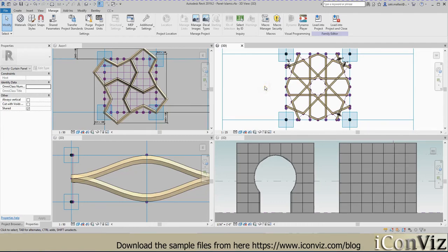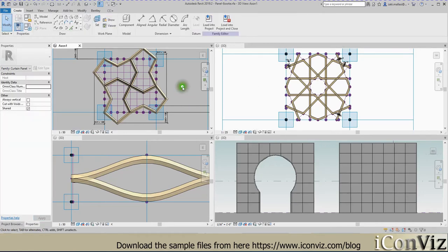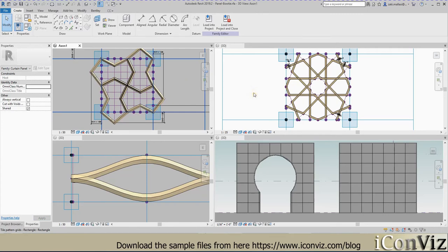In today's tutorial, I will focus on two topics when generating dynamic facade in Revit. The first topic is to be able to construct different 2D patterns with different themes, as you can see here. This is accomplished by using a simple technique of creating an organized network of lines inside the curtain panel pattern-based family. And here I'm showing a few examples of panel styles: an Islamic, a contemporary, and a curved 2D pattern. At the same time, I will explore how to include parametric controls for the geometry.